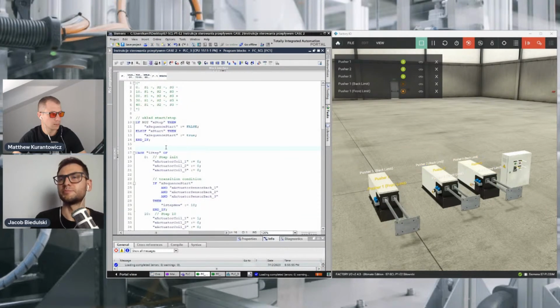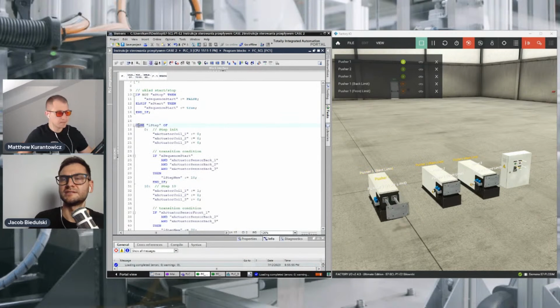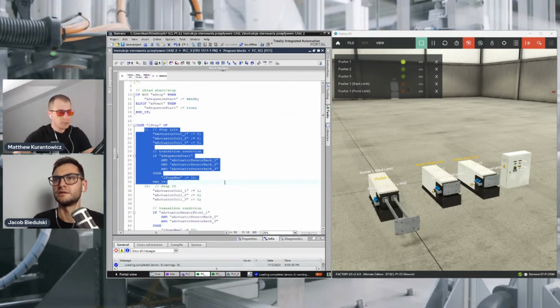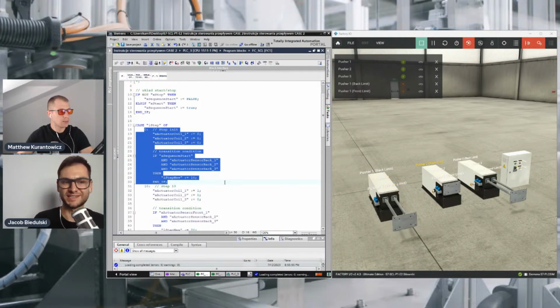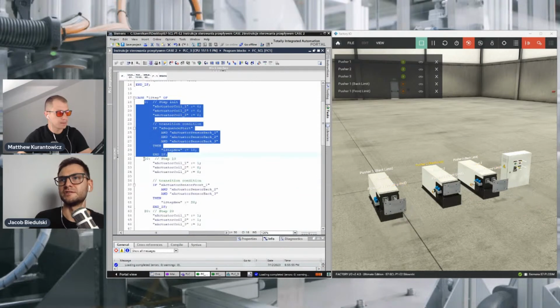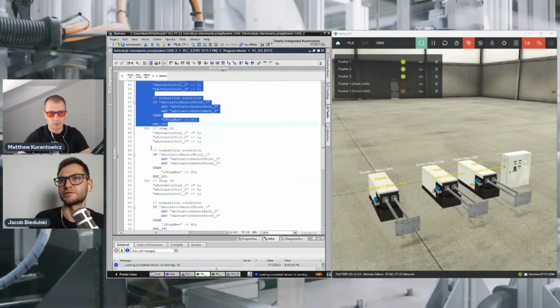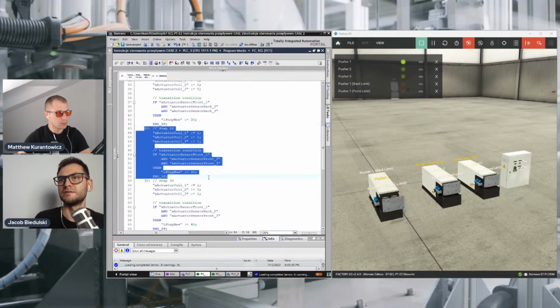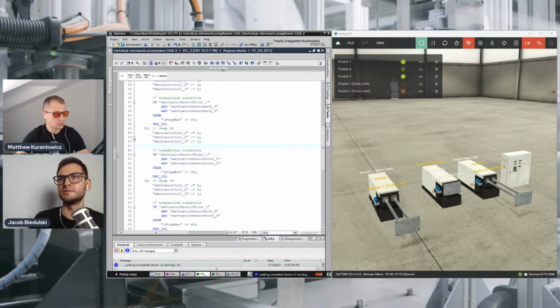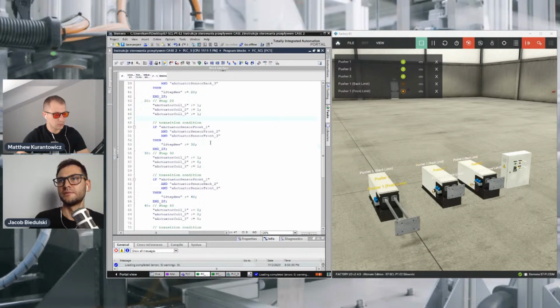Case instruction is perfect for programming a linear sequence because in this instruction, only one section can occur when this instruction is executed. So you define different steps in different sections of this instruction. And in every section, you define code that should be executed in this step.